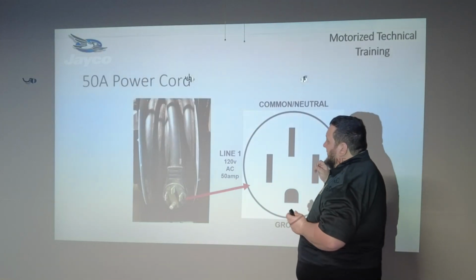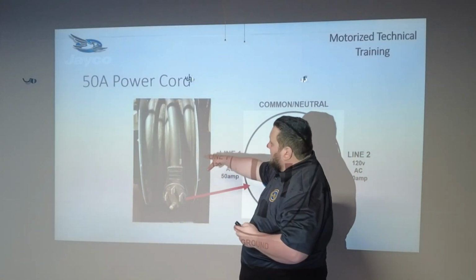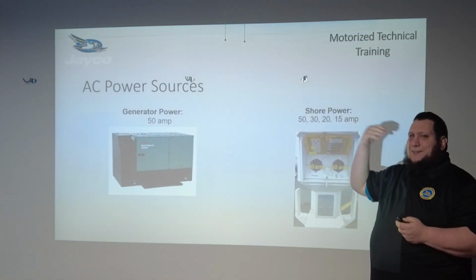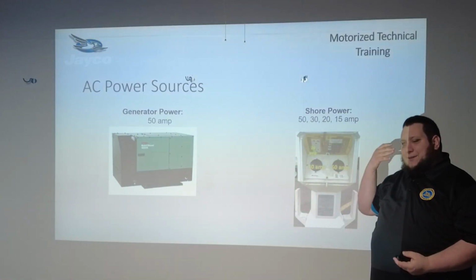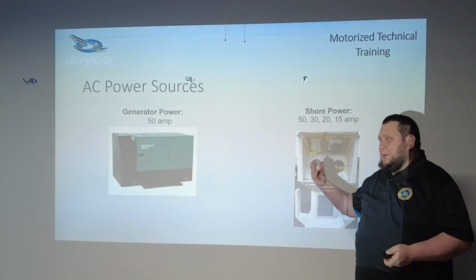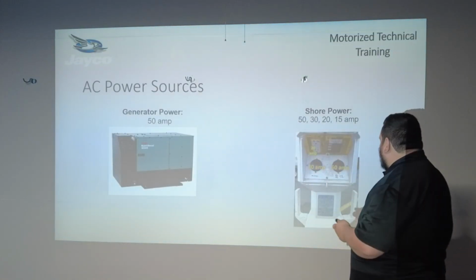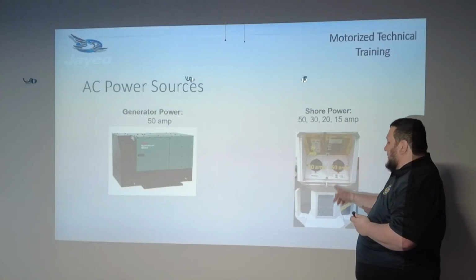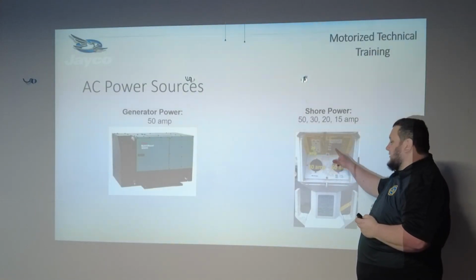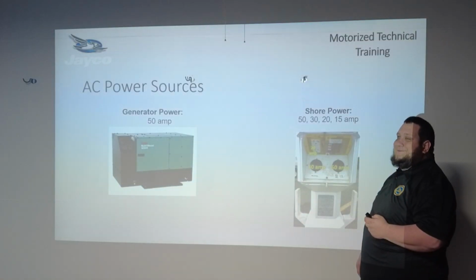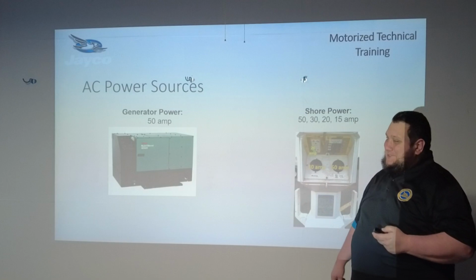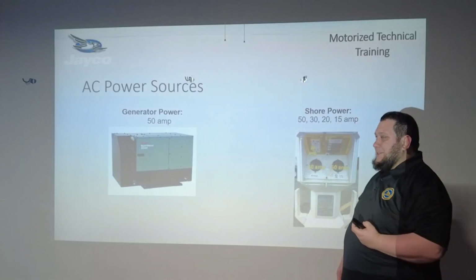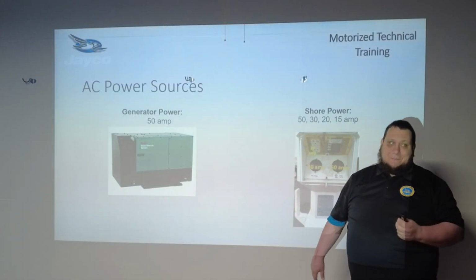An important thing that I want to bring up when we're talking about our power cord here and when we're talking about plugging in to our shore power pedestal. It's one of those things that once you hear it and you think about it, like, well, yeah, that's common sense. Why wouldn't I do it that way? You'd be surprised how many people don't. You got breakers right here. Every pedestal is going to have a breaker. Before you plug in your power cord, turn that breaker off. It's one of those things that you hear it and I'm like, well, why would I plug it in while it's live when I can turn it off? But people do.